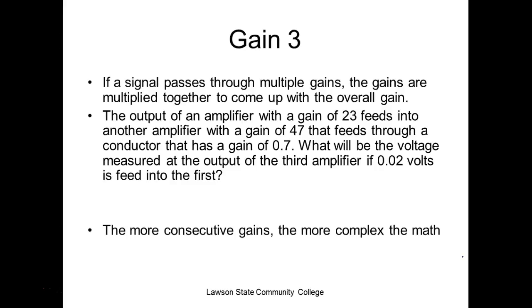So it's just like if I tripled your salary and tripled your salary again, I'm not increasing it by 6, I'm increasing it by 9. Right? You understand? So if I was giving you $1 an hour and I said times 3, that's going to give you 3. And then I say I'm going to triple your salary again. Well, that's going to be 3 times 3, that's 9. A lot of people say gains are added together, but gains are not added together. Gains are what? Multiplied. Y'all understand that?